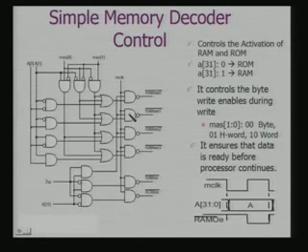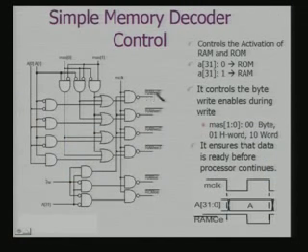That means, depending on the size of access, I may like to write a byte at a word location. So, if I am writing a byte, then I am activating a particular RAM. If I am writing 16 bit, I shall activate two of them.